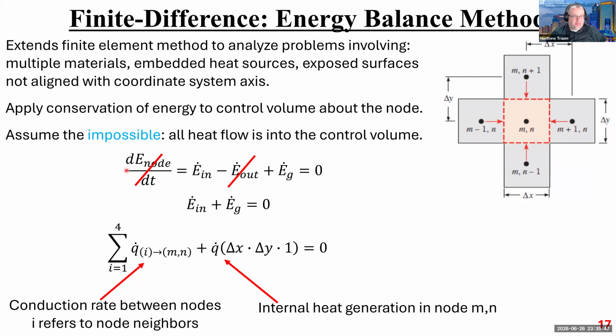So here is my first law of thermodynamics for this node, right? Here's my control volume surrounded by my dotted control surface. I have 4 heat fluxes entering, and remember, we're solving this for heat generation. Where is heat generation? Embedded heat sources, right? So heat generation. And so if I write the first law of thermodynamics in steady state, here's my first law in all of its glory.